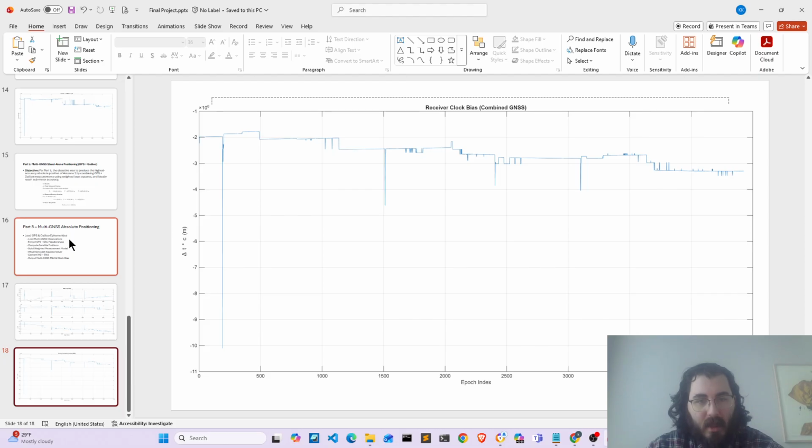So the final summary across all parts. As a summary, the project demonstrates which components of GPS positioning are robust and which are extremely sensitive. Part 1 performed well because the differential methods cancel many errors, and part 2 and part 4 failed where essential GPS corrections or correct geometry modeling were omitted. These results highlight the importance of accurate satellite modeling, proper timing, and rigorous measurement processing in any GNSS algorithm. And that's all.